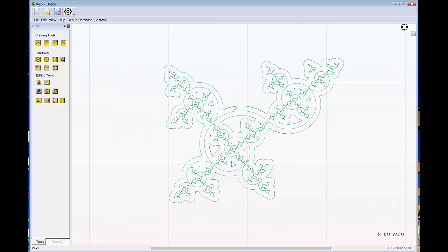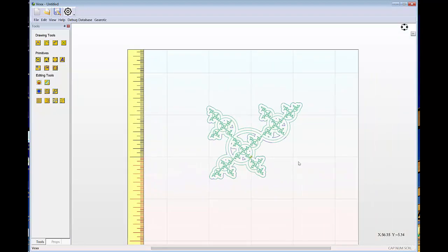So as you can see, the offset did fairly well. The result is comprised primarily of arcs by the look of it. I don't see any orange, so it doesn't look like any Bezier curves were adopted in the offset. But it's offsetting both to the insides and the outside, and can create a nice looking graphic depending on how it's done. I just mentioned that so that you know that you don't have to offset small sections at a time or anything.